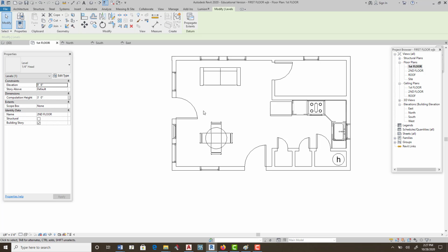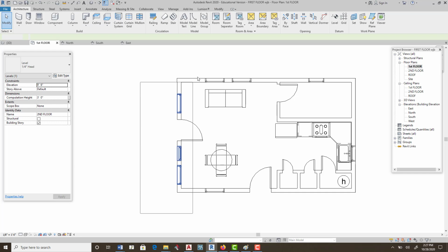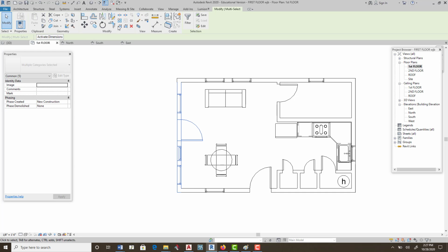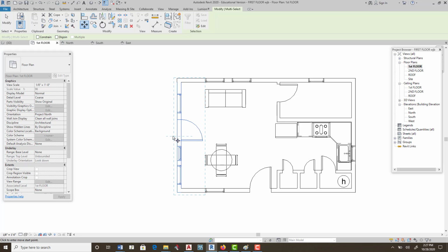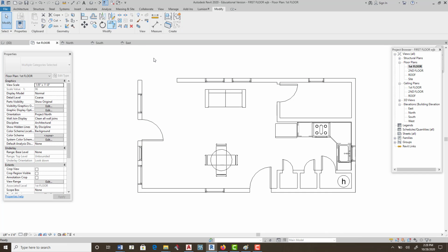And what we're going to do is extend this out if we want. So if we want to, we can just make a window around there, okay? And we can go to move, and we can just drag out maybe 5 feet 6. Look at that. And sometimes there's an error. It says Revit could not keep these walls joined. That's okay. Just say unjoin them. I agree. Unjoin them, because all I can do now is come back and select and select.